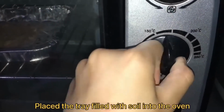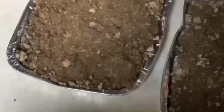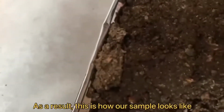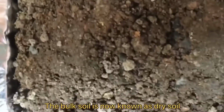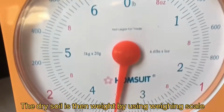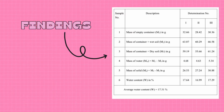Place the tray filled with soil into the oven and leave it overnight. As a result, this is how our samples look like. After being placed overnight, our wet soil is now known as dry soil. The dry soil is then weighed by using the weighing scale and known as M3. This is the water content determination that has been obtained in the expected result.